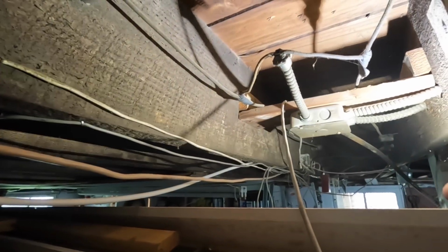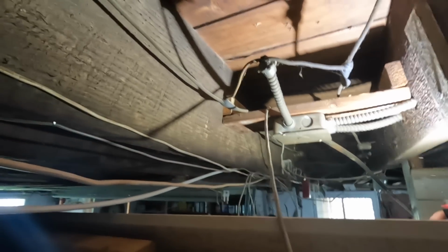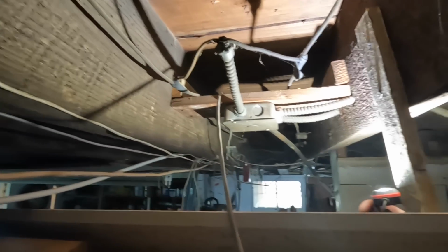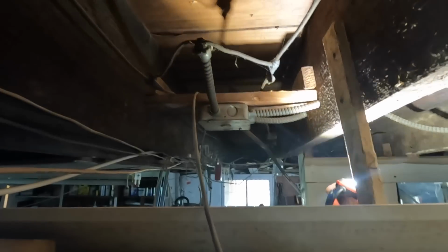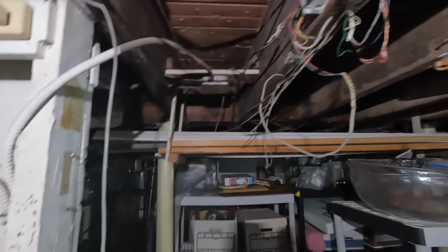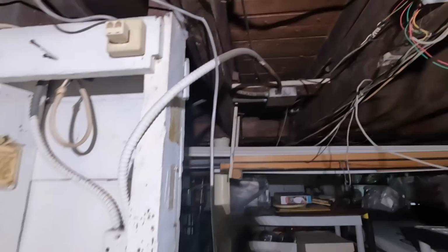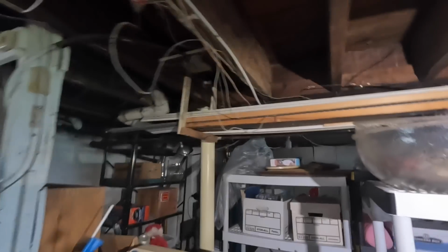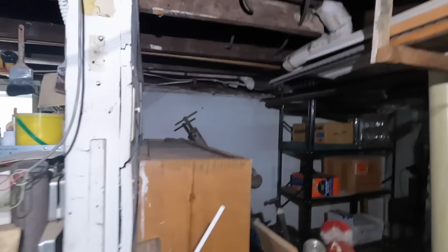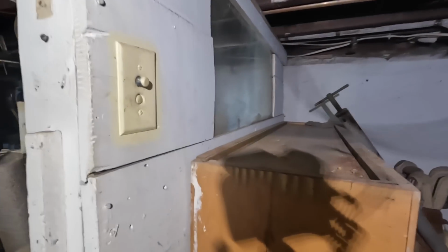Like I said, this is the first time I'm watching this video back. So there you can see how they did it. It's somewhat of an improvement to have protection around the cables. But obviously that's not very safe like that, especially if there was a problem with the circuit and it started arcing. That would be a big problem. Nowadays, we have splices inside of a box, as you see there. Anytime you see a flying splice, definitely not a good electrical installation.